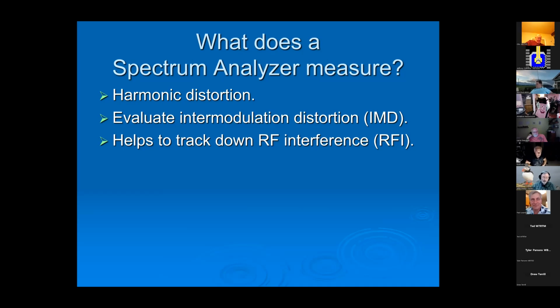With a portable spectrum analyzer, you can go to the power pole, you can go to your neighbor's grow lights, you can walk around the house, see if you have a wall wart that's spinning off a whole bunch of hash. That gives you the ability to track down that problem in the spectrum of where you're experiencing that RFI.